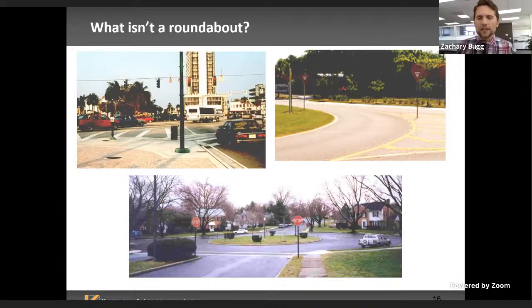With a stop sign, you don't have to worry about signal phasing and lost time. But presuming that everybody comes to a complete stop like they're supposed to, that flow, as you mentioned, really decreases because you need that additional gap between vehicles to accelerate from a stop condition. So that yield sign is really where the magic comes in for roundabout operations and one of the biggest benefits.